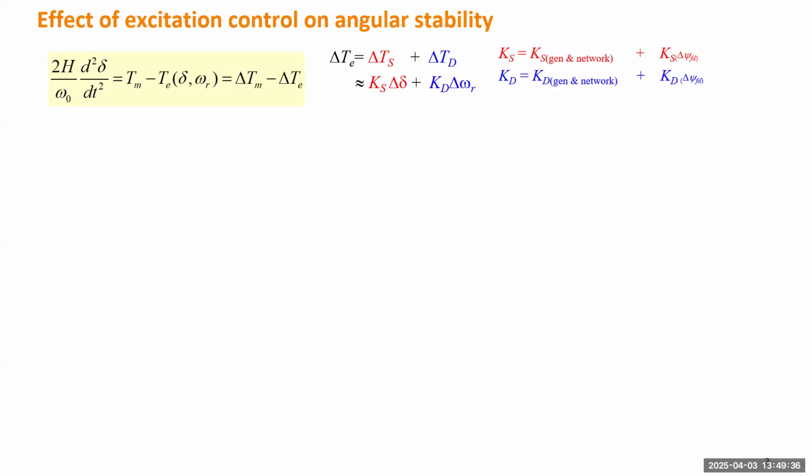Why do we have to split in such a way? Because for any power system or generator, if it is well designed, the first component has to be positive. Otherwise, you have a design problem. In today's system, we don't worry about the first component, but the second component can be a question. If we don't have an exciter at all, we have a constant field voltage or constant field current, which is equivalent to having the gain Ka in the AVR be 0, or a very small number. It doesn't do any control at all.